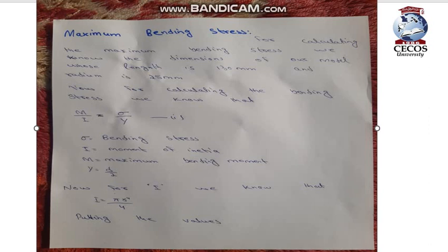We have to put these values in our bending stress formula, which is M by I equal to stress by y, where the stress is the bending stress, I is the moment of inertia, M is the maximum bending moment, and y is actually diameter by 2. For I we know that I is equal to pi r to the power 4 divided by 4. Putting the values will give us,